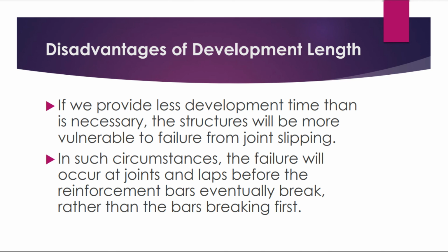Disadvantages of development length. If we provide less development length than is necessary, the structures will be more vulnerable to failure from joint slipping. In such circumstances, the failure will occur at joints and laps before the reinforcement bars eventually break, rather than the bars breaking first.